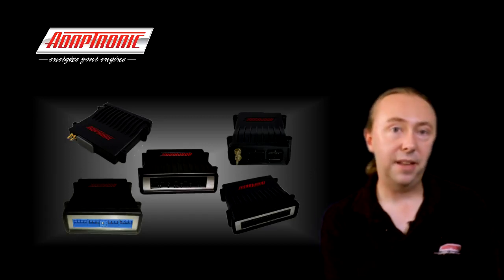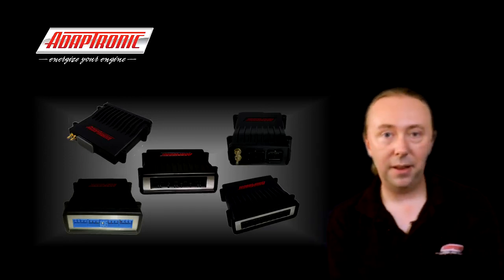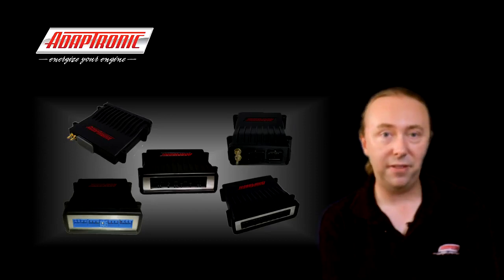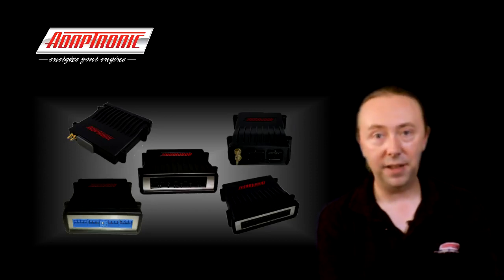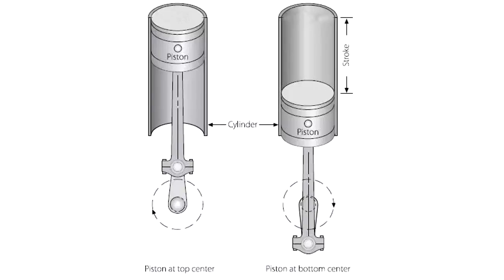You could actually do the same thing on the RB26 GTR engine, because the front half and the rear half have each got their own oxygen sensor, so you can run it as a separate bank engine that way. And similarly with a 13B, you can run a separate exhaust manifold pressure off each rotor and run each rotor independently. Finally, the firing mode can either be 4-stroke or 2-stroke.